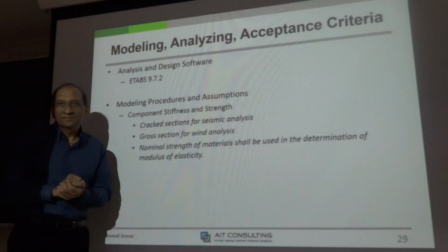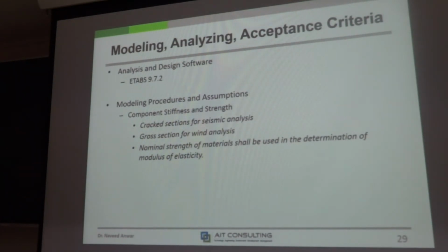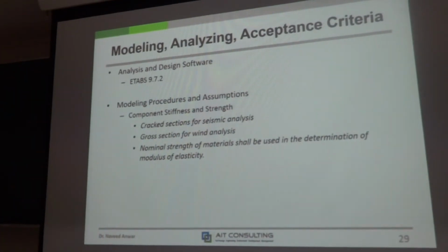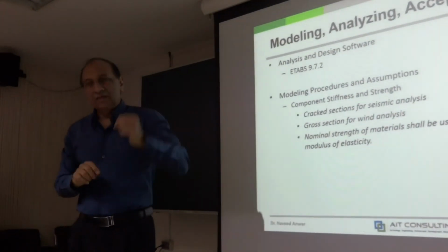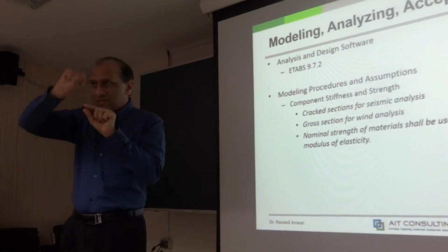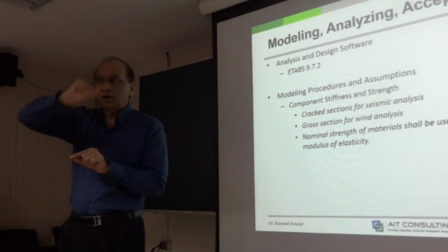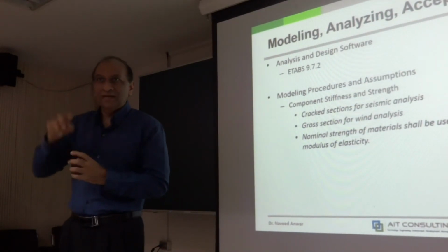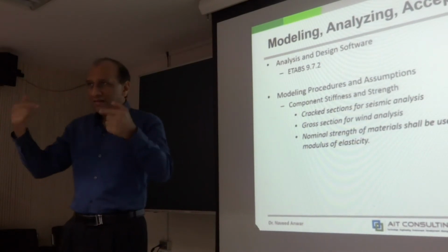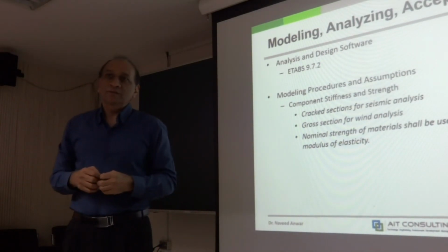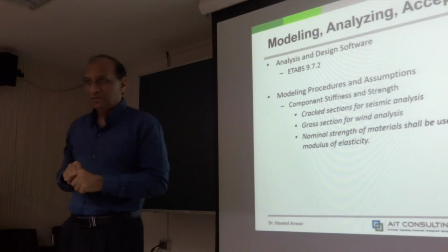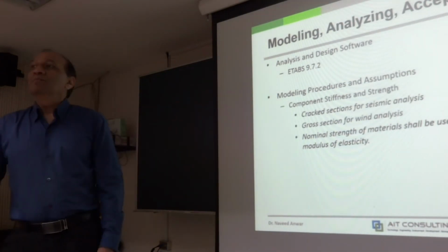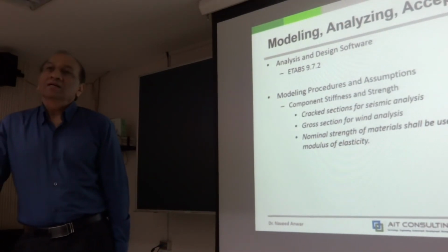And why are these important? Because they completely change the results. For example, if it's a frame, an indeterminate structure, and I apply a load, and first, the moment of inertia of all members is equal, and I calculate the bending moment in column and beam. And then the second time I multiply the moment of inertia of the column by 0.5 because I think it's cracked. What will happen to the bending moments? Moment will increase in the beams, right? True. Why?